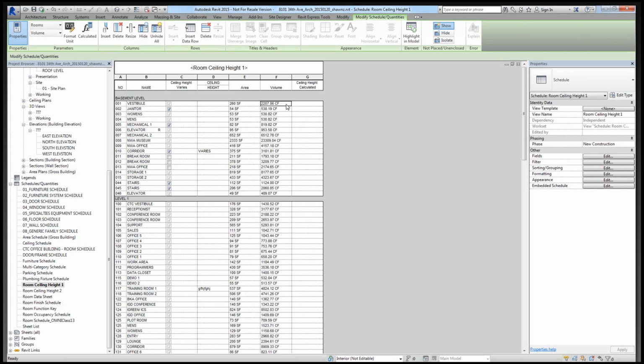In some cases, if there are multi-elevations of ceilings, I would get some random weird numbers inside of there. It's not the top elevation, it's not the bottom ceiling elevation, it's some average in the middle based on how much of the surface area is high and how much of the surface area is low, and it's really inconsistent with the results I got back.